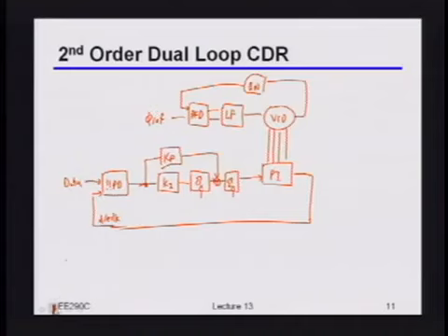So again, just to make sure the intuition is clear, this register here would be the frequency register, and that output over there would be the phase register. So the frequency register tells you what that ppm offset is between the two clocks. And the phase is telling you what's actually the instantaneous phase value that you should be using to then, of course, control this phase interpolator here. Okay? Does this make sense to people?